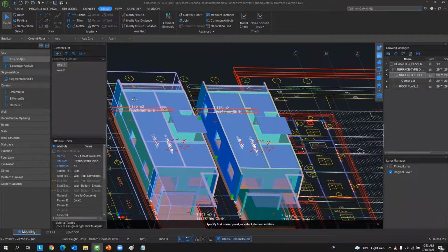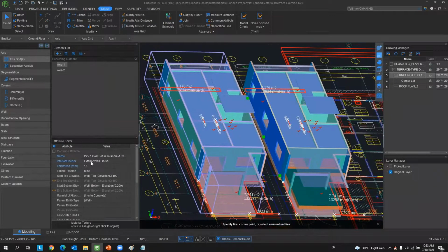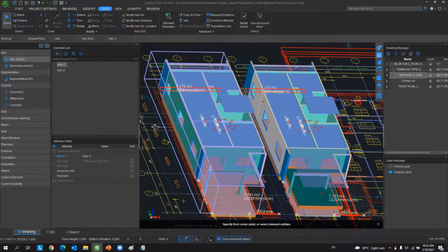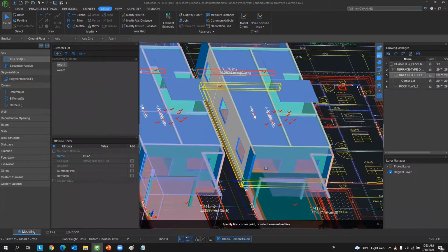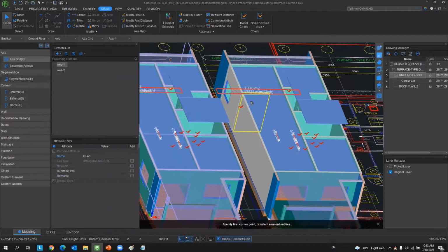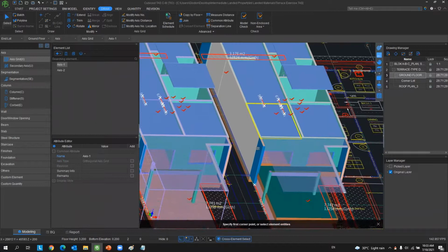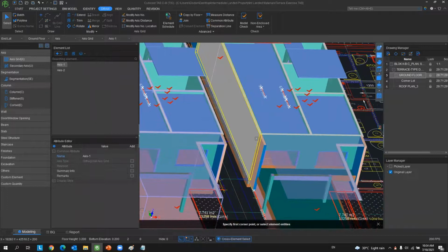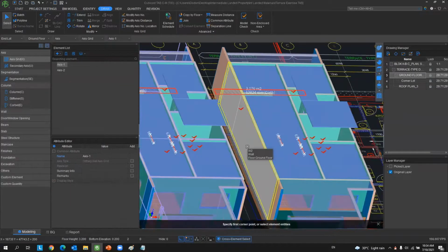Let me just open this one. I select, and it will be the whole piece of the entities. They will be our external wall finishes. I just press delete to delete the finishes of it. And I select the opening, press delete, to delete the window as well, the wall opening. And also for the column, I do not need these finishes because there will be a duplication. I also just select and then click delete.